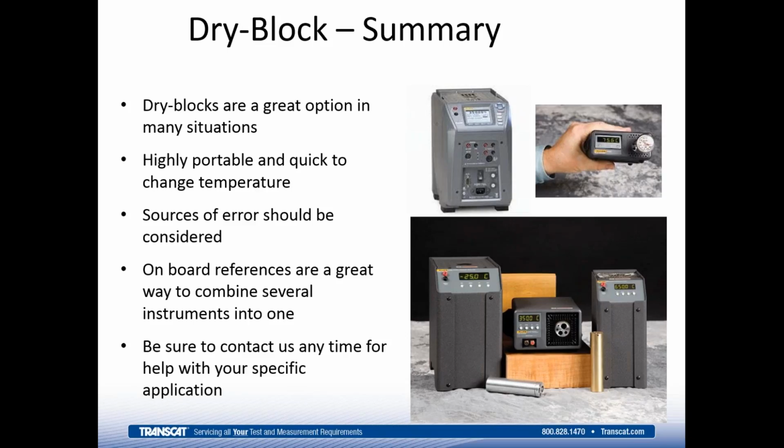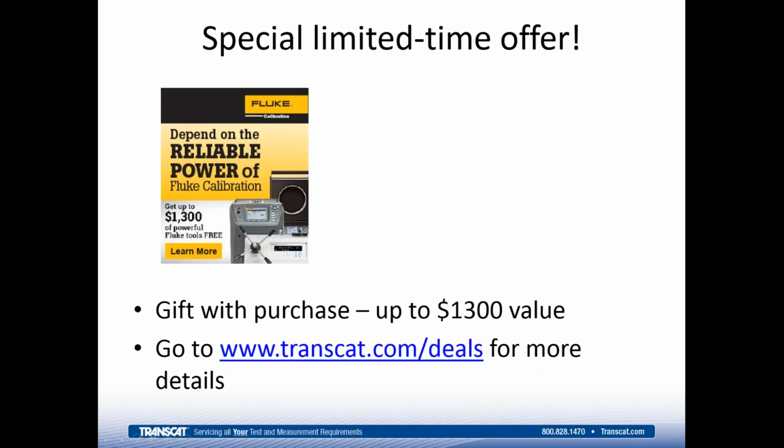And in some cases, at certain temperatures, you're going to need an external reference just to get to 1/10 of a degree. But for most applications, the dry block itself is going to be accurate enough. So that would conclude this part of the seminar.